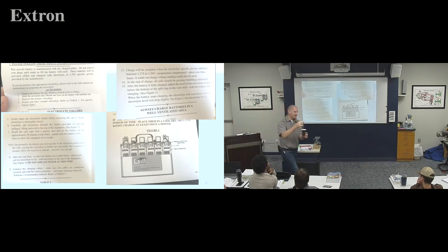So that tells me my density of this battery acid is somewhere between completely charged and discharged. So if this was completely charged, I would have all 4 floating up at the top. So right now, the red and the green are more dense than my fluid. As my fluid gets denser and denser, the red and the green are gonna go float up to the top.